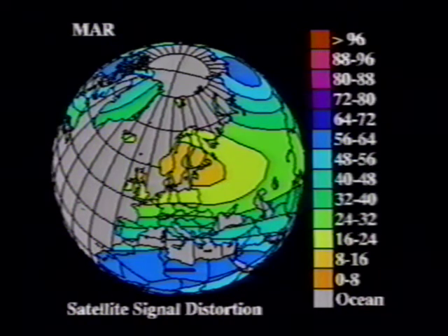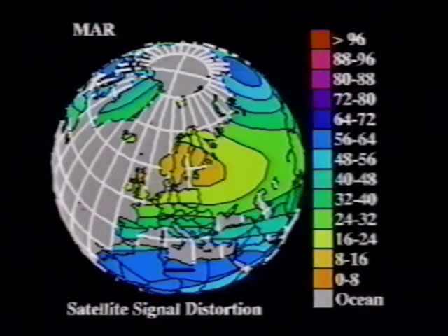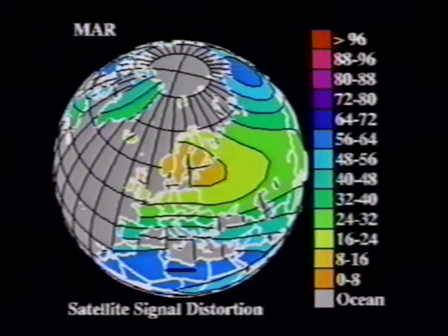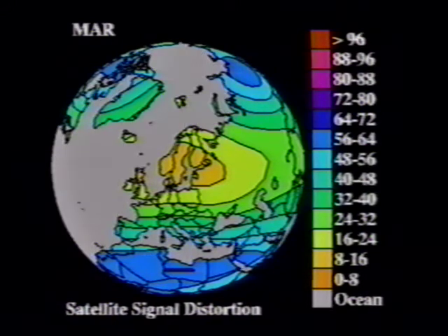In our globe, we have several sets of lines which clutter the image and contribute to chroma. Latitude and longitude lines, contour lines, and map boundary lines. We recommend removing outlines to simplify the image. As we remove them, notice that the shimmering along these lines is greatly reduced and the image appears less cluttered.